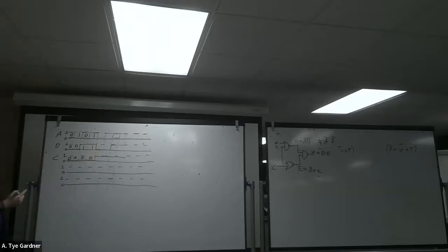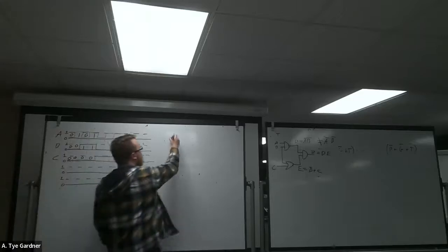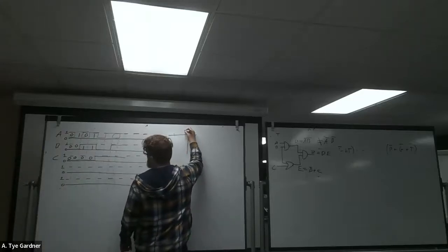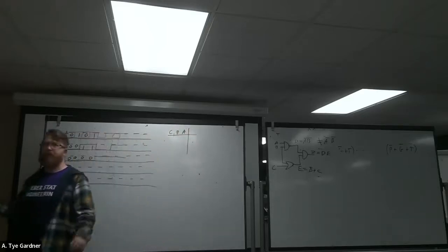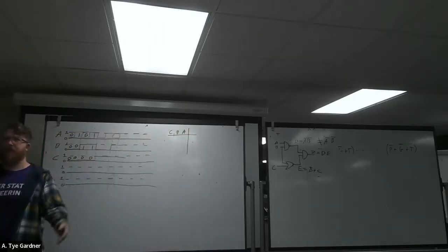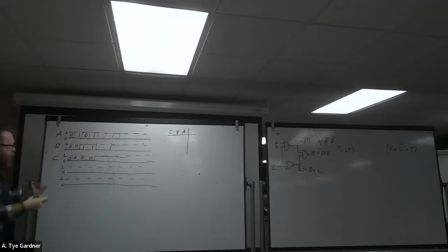You'll notice that the binary counting, if you paid attention to the columns, goes up from C when I did it this way: 0, 0, 0, 0, 0, 1, right? So just be aware that when I did it this way, it's the reverse of what you might expect in the truth table, unless I draw the truth table with C changing the least often, which is what this approximates. Okay, does everyone see why? It's just something to be aware of, because as long as we keep things straight and are careful, the order doesn't matter.